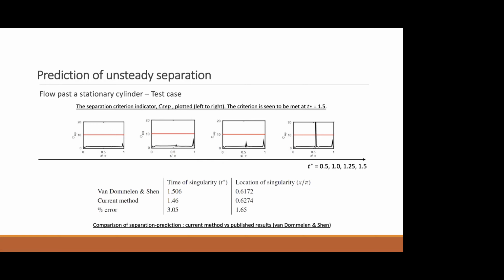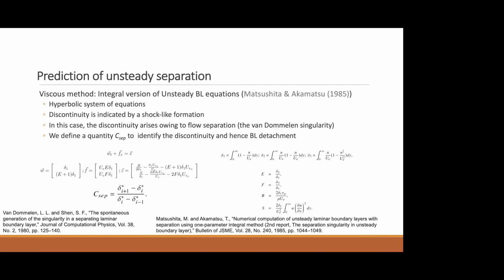So first, you're using the integral boundary layer equation to predict the separation. Flow separation is proven to be very difficult to predict, and a number of factors can affect the separation point. Like one is the transition. I noticed that you're doing this at a very low Reynolds number. So can that equation treat phenomena like the transition?